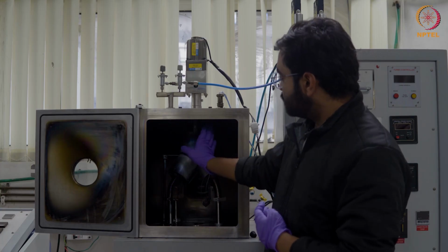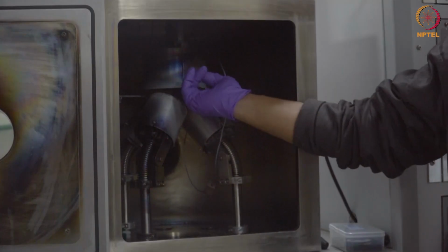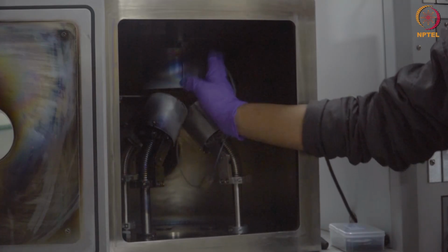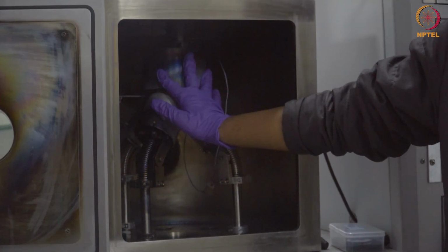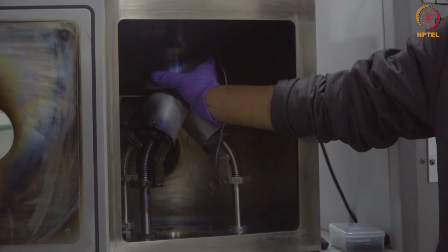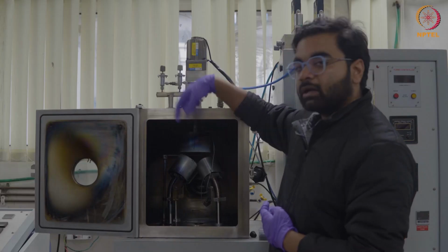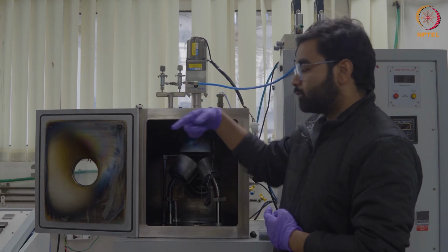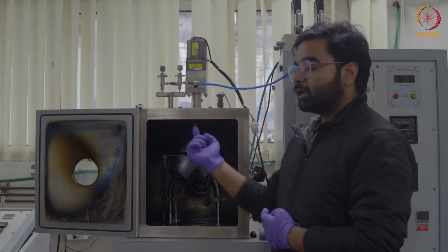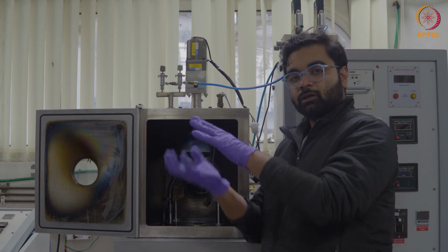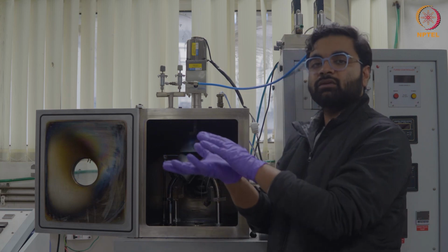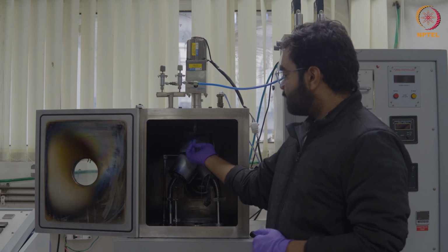So what we do is create this vacuum. You see this is the surface. Here we place our sample. And what you are seeing over here is a substrate heater, so we can do substrate heating, as well as a rotator. It will rotate the sample continuously. The sample that would be placed over here would continuously be rotating in order to get a uniform deposition on the surface. So this will have a rotator unit.